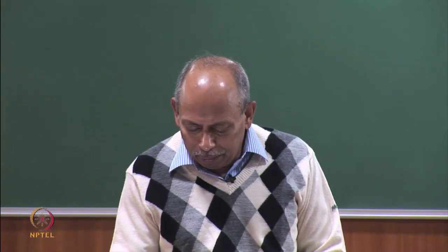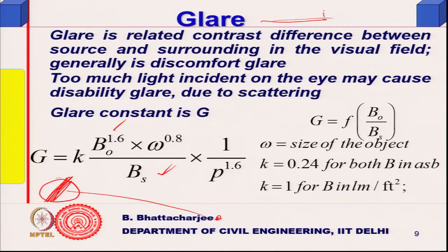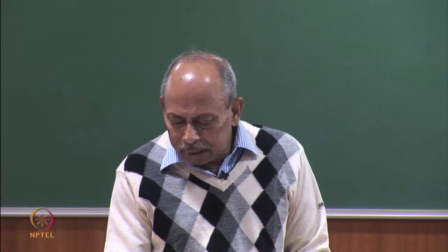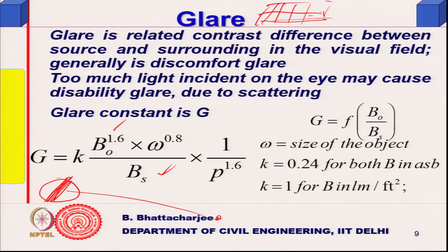So, for example, if it is a flat rectangular lamp, no louver, the size will be full size, right, and brightness you can of course find out from the lumen output of the lamps that are inside. If there are some louvers like this, then the effective size will become this much each one. So, each one separately has to be considered and summed up, right. But then angle would change for each one of them, because if somebody is viewing from here, these angles are different. So, position factor will actually change a little bit. So, that is how we calculate glare, right.